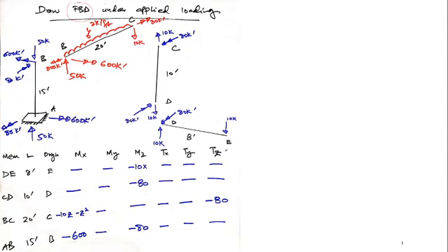Okay, starting with the free end, I have a 10 kip load in Y direction, and I have to balance this. So I'll balance it with a vertical 10 kip. You should know that this is in Y direction and this member is in X direction. So there would be a moment in Z. Now you should know the combination is that the load is in Y, the member is in X, and the moment should be in Z.